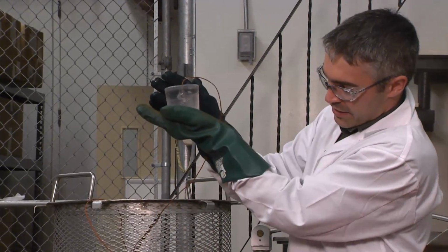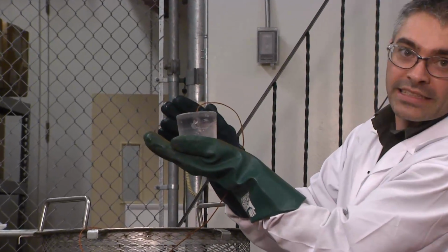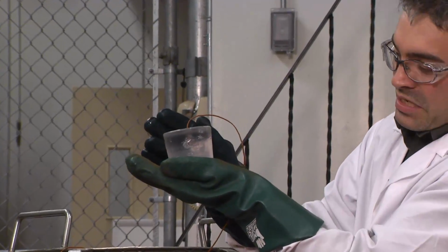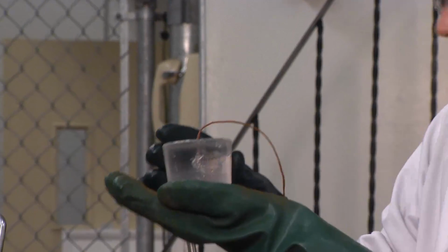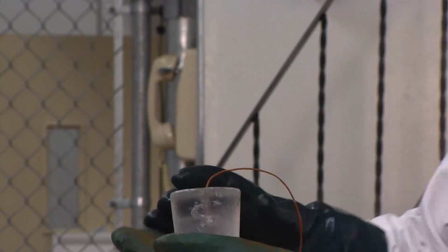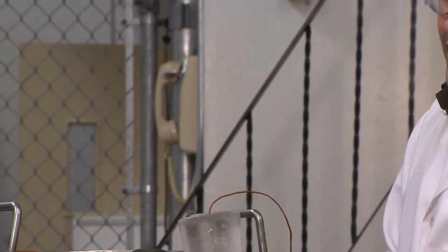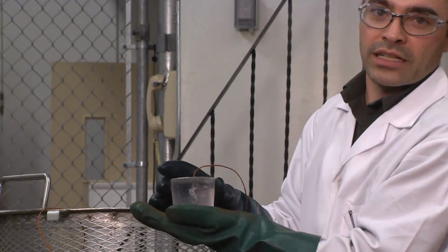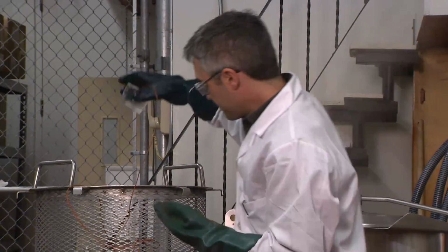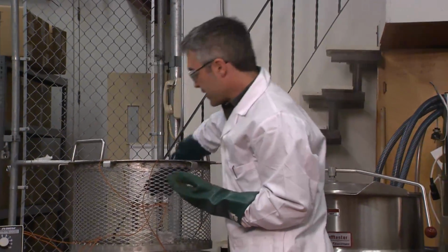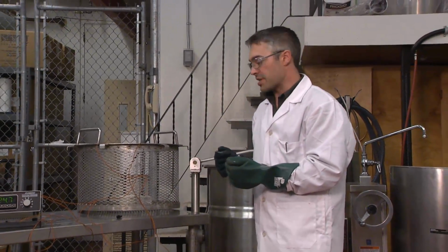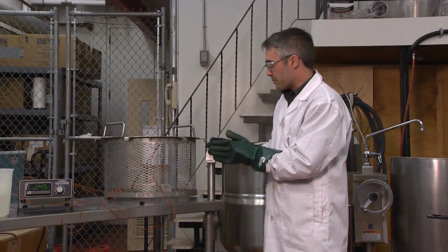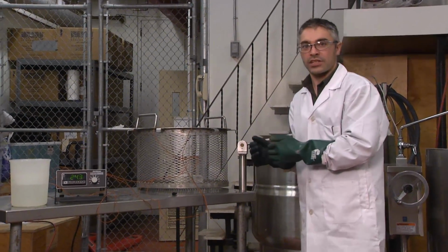The thermocouple, as you can see in this one, is embedded directly in the center of the object. When the center of this object reaches 100 degrees after being plunged into the kettle, at that point you'll be able to pull it out and you can assume that you're at equilibrium. You'll be conducting the experiment for all of the shapes all at once, and it will take some time for the thermal gradient to pass all the way into the center of the object.